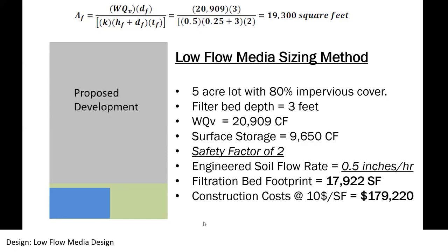What depth of ponding is allowed in this bioretention basin? So typically, you're going to see 1 foot of ponding. I know in certain municipalities, like in Harris County and Houston, you can go up to like 3 or 4 feet. But yeah, that's pretty much your limit, is probably 3 feet.